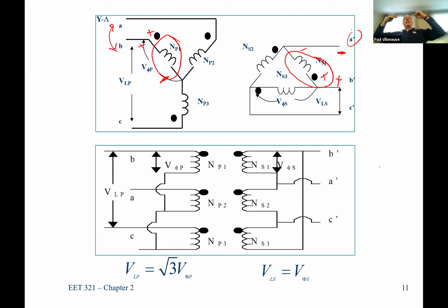In a better setup, those two would actually be in phase with each other, so that in case the incoming power at the top of campus was out, you could run more of campus on the bottom circuit. Usually it's the other way around. The top of campus tends to be more reliable than the bottom of campus, and you could run all of campus off of this top section. They want to have that backup one down below campus to give a little bit more reliability and redundancy.